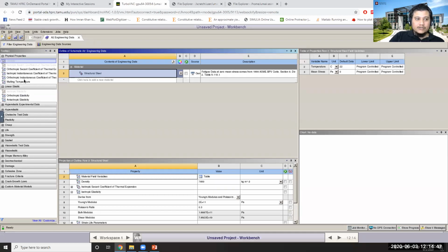All right. I'm not going to go through all of them and explain what each option does, but some of the most important ones are, for example, in the case of physical properties, you have density, coefficient of thermal expansion, melting temperature and stuff like that related to the physical properties of any material. Then the mechanical behavior in the elastic region.